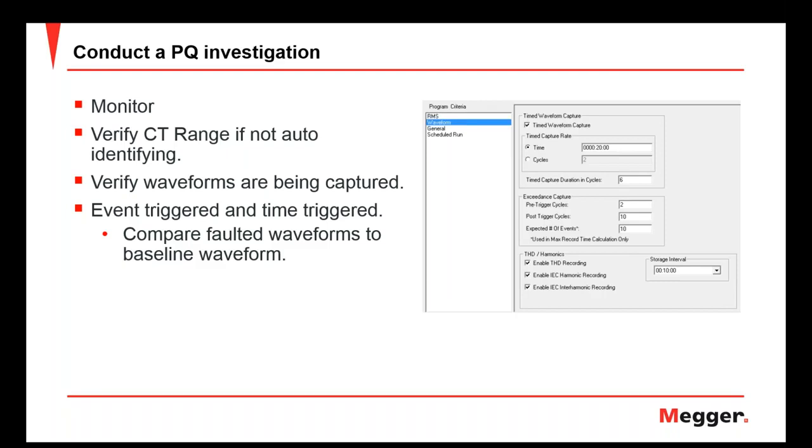So they have a lot of value in that they give you a baseline reference to start with. And also it's ideal for doing a harmonic analysis, because a detailed harmonic analysis on a time-triggered waveform will let you know what your load is. Again, I don't have enough time to go into that in this presentation, but in future ones, we will cover more about analyzing harmonics and determining your load based upon the harmonic content of the timed waveform.